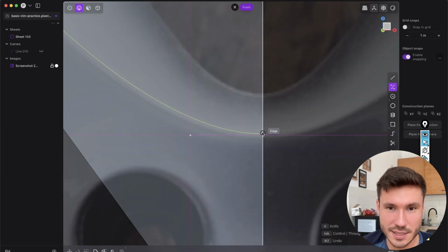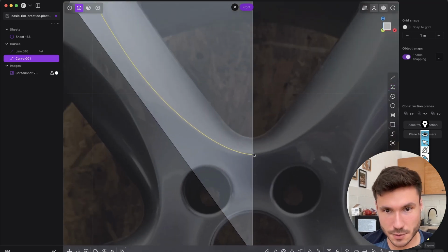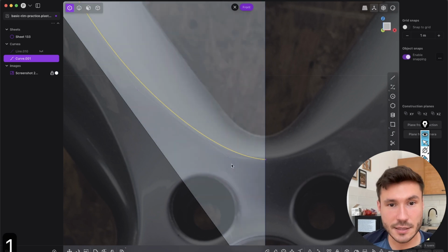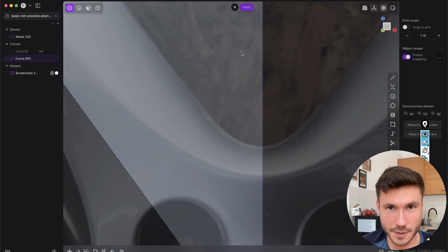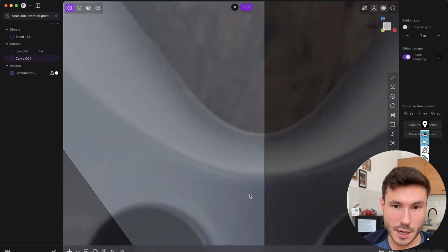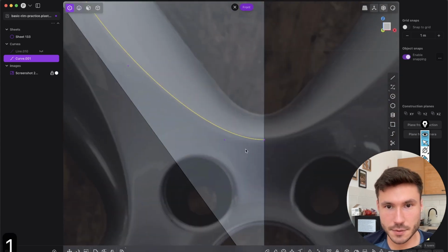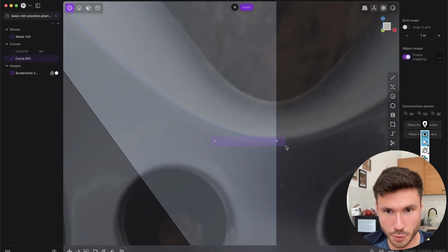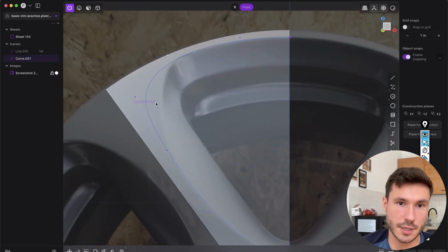So what I do in this instance is I just go somewhere, just snap here, right? This is where our shape ends. And you can just take this point and adjust it afterwards. That's also fine. You can do it both ways. So if you select this point, press G for the move, and now control click to this point. And now if we bring this curve here to the front and jump in here, you see those two points are on the same height. So now that's fine. And now you can just start to adjust this shape a little bit.